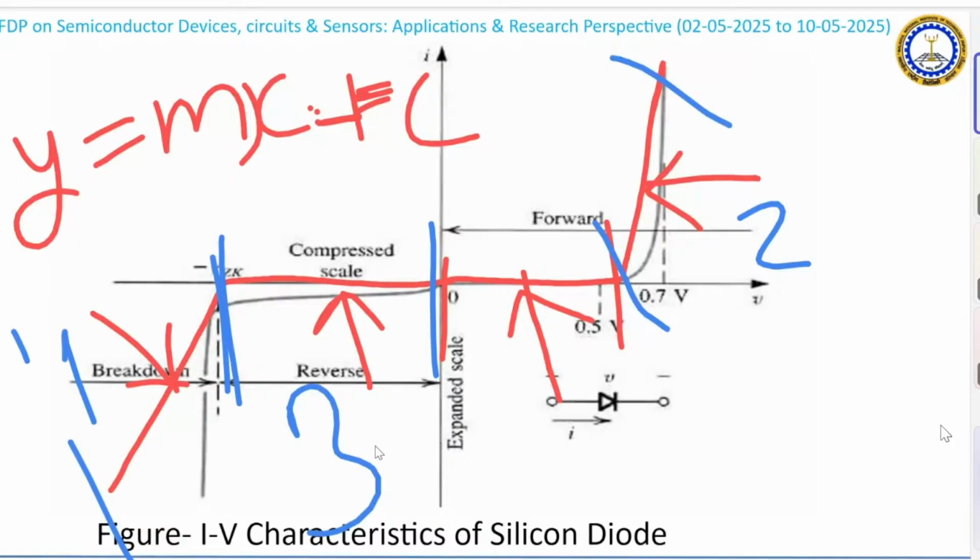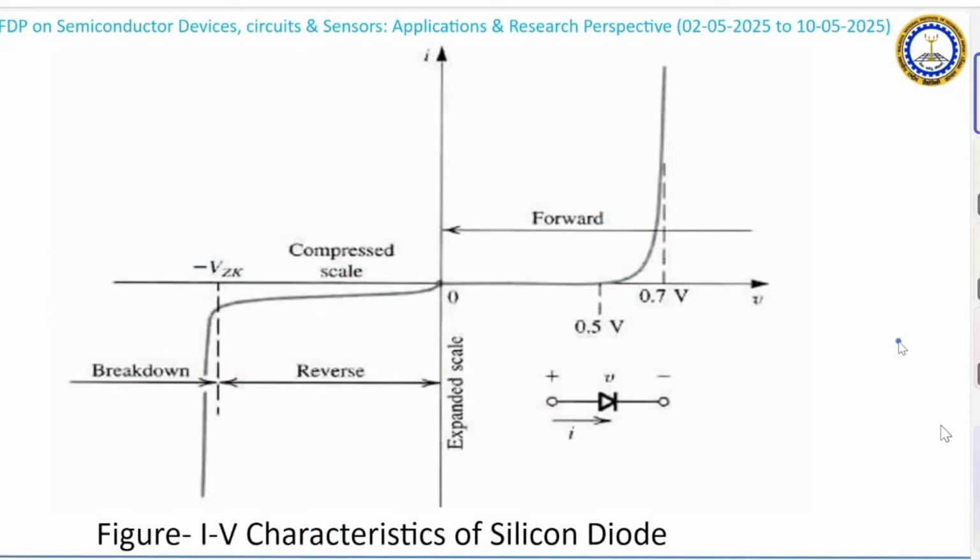So it means the 0.7 volt or 0.3 volt, which was the minimum required voltage to turn the diode on, is negligibly small, right? So we can omit that portion and let us take the theory of the ideal diode. In the ideal diode, it is good practice to make non-electronics or non-electrical branch engineers study the ideal diode characteristics, which helps them to solve a number of examples.